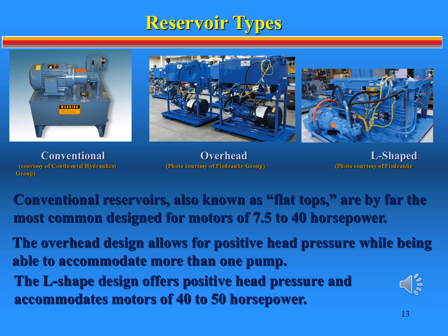Components are typically welded or mounted to the top of JIC reservoirs, such as pump and motor groups, filters, heat exchangers. You can also mount a JIC reservoir on an elevated platform, which provides the below-mounted components with flooded suction and ease of access. Be aware that leaks in above component tank designs are exacerbated by gravity.